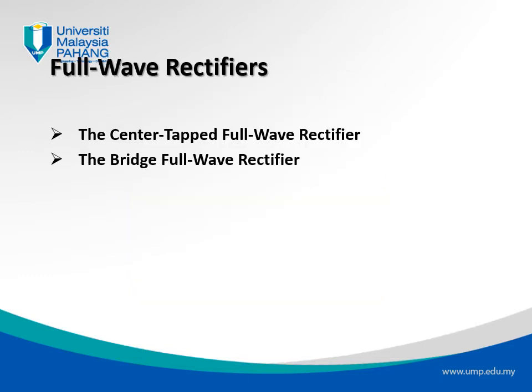So now that we have finished the section on half wave rectifiers, I think we can note that the main inconvenience of the half wave rectifiers is that the average voltage is much smaller than the peak voltage. So in order to be able to capture a higher level of voltage when we go through a rectifier, instead of using a half wave rectifier, what we can do is we use a full wave rectifier, right?